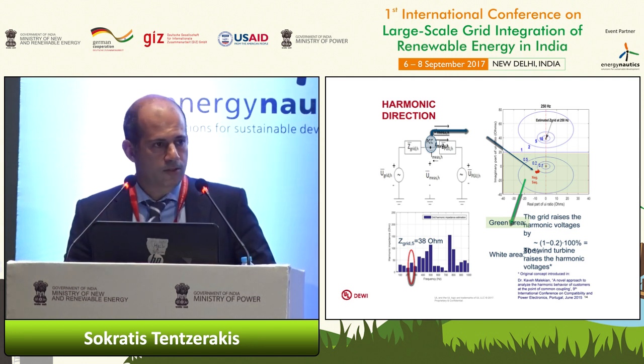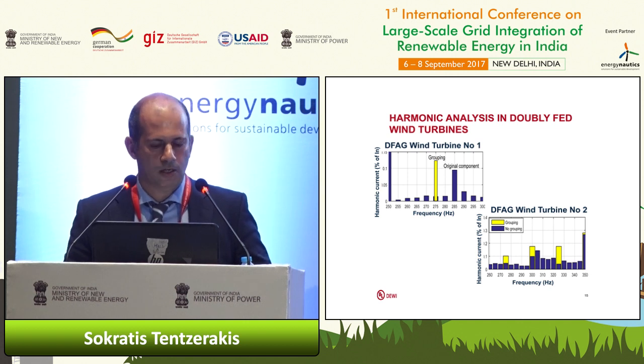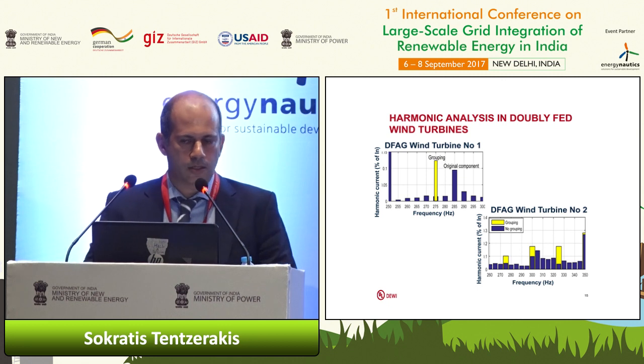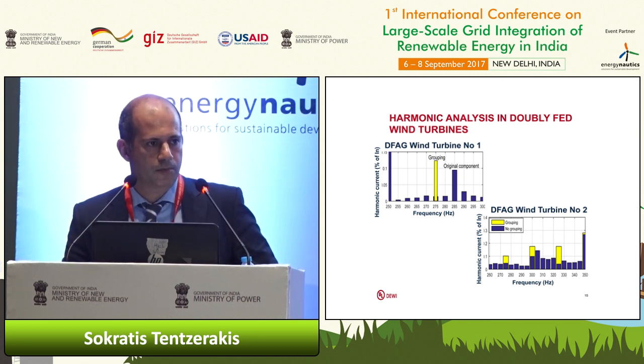Finally, it is worth mentioning that with the grouping procedure of the IEC, which focuses on the magnitudes of the harmonics, we concentrate the harmonic energy content on one single harmonic. But in the case of double-fed machines, in the low frequency range, we have harmonics which are slip-related, so they are slightly shifting.